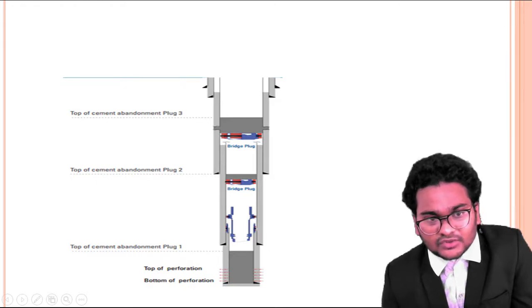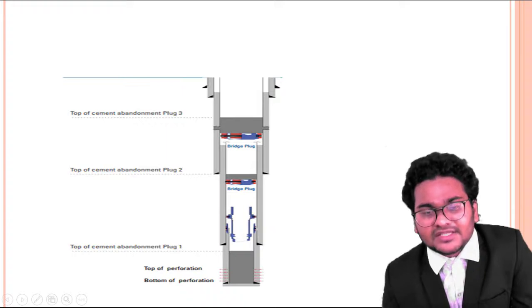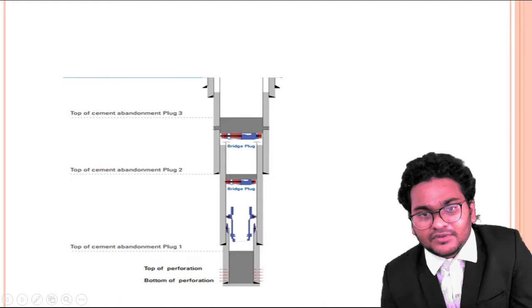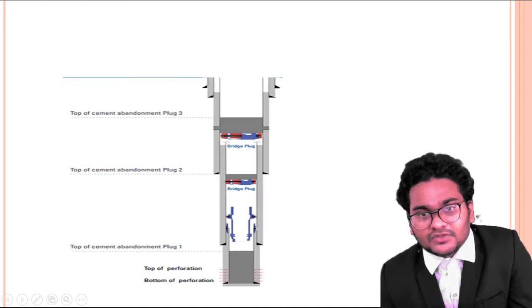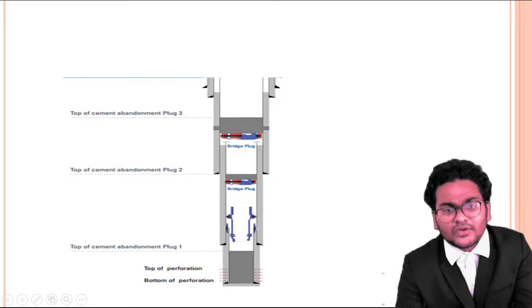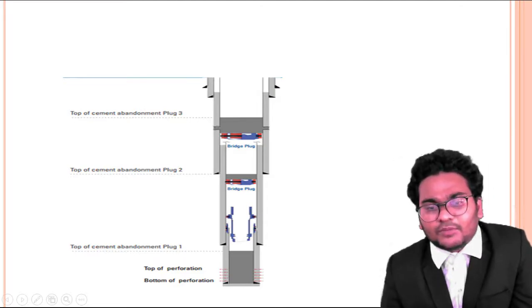I'm closing it; this is the top of the cement. Up to here, I have done the cementing. I send the cement and give it some time for setting up, so automatically this is already closed. Then I keep one bridge plug here. The bridge plug is a plug that does not allow anything from the bottom,